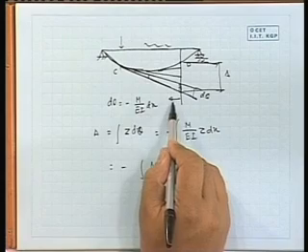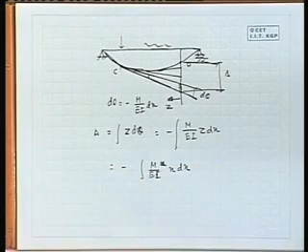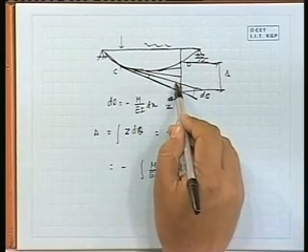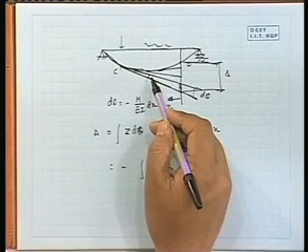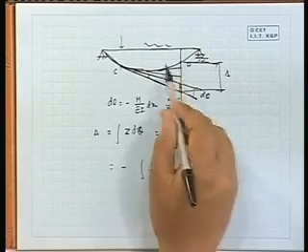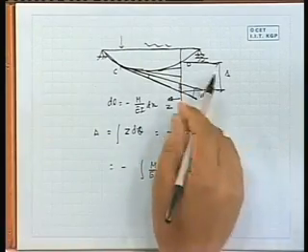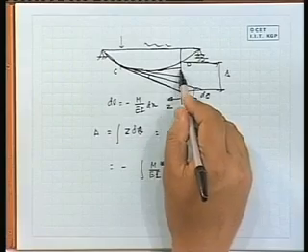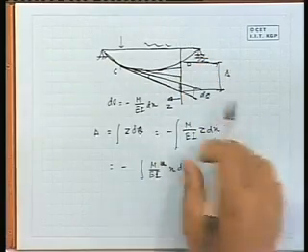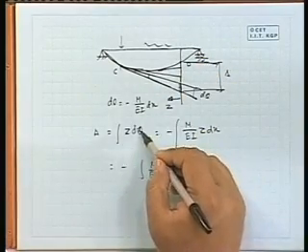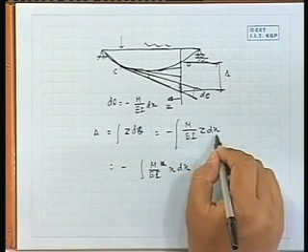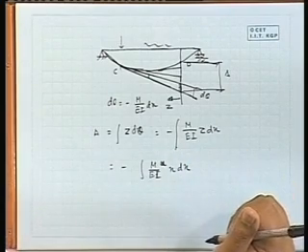Say here we are trying to tell it is z, right. So d theta into z. Now if you take the next one, it will be a different z. Yes. Okay. So you have to go on accumulating, definitely you will get this value, this value, this value, this value, finally you will get the total value. Okay. So it is, and d theta from your earlier expression we have put M by EI into dx.